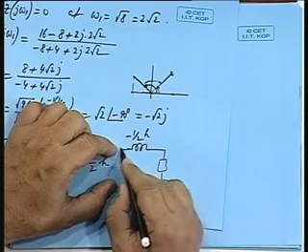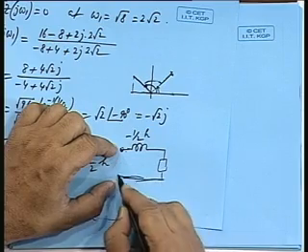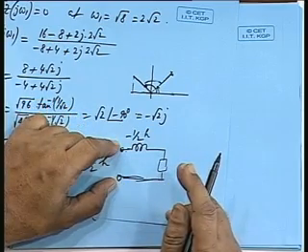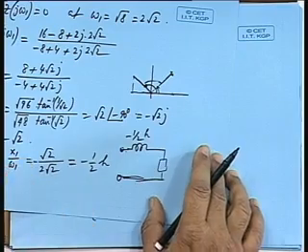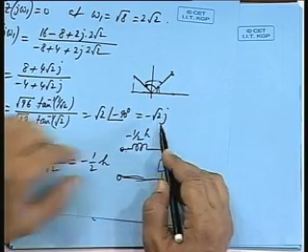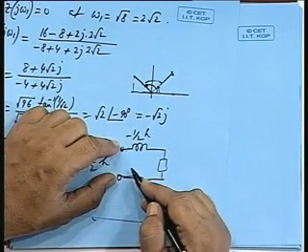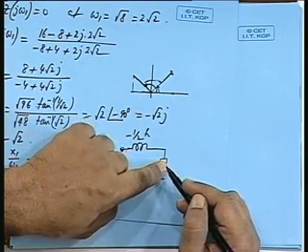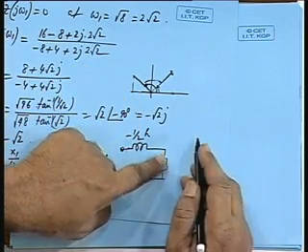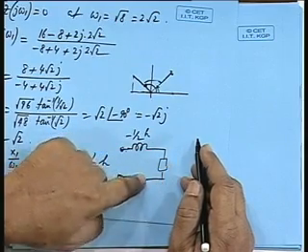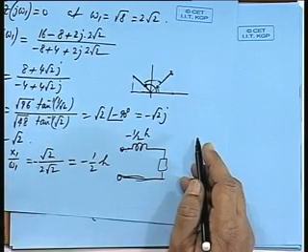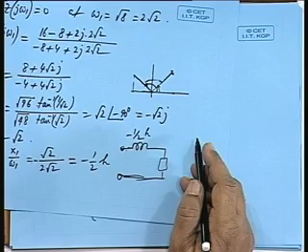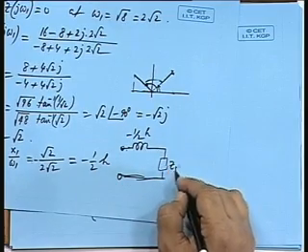If you remember in the network, this function Zs has a value of minus half root 2j at that frequency, and it is also the value of this that we have equated. So, this will be a 0 at that frequency. If you remember, this element Z1s must be 0 at that particular frequency, omega 1. So, this Z1s